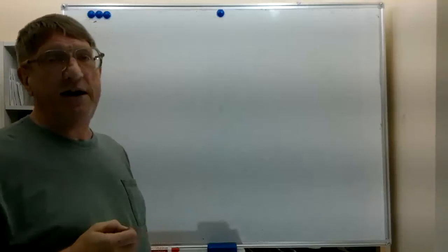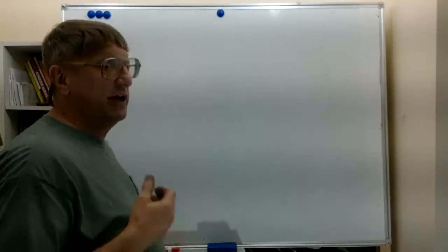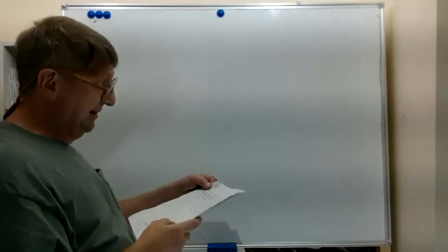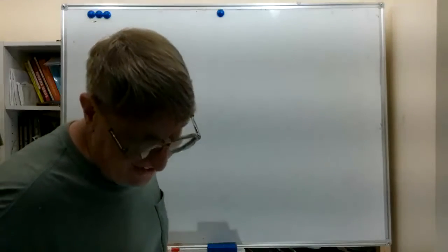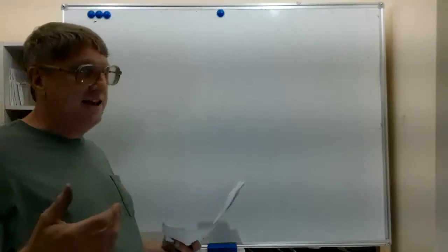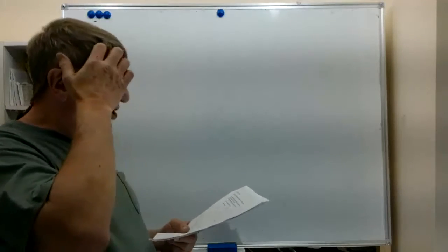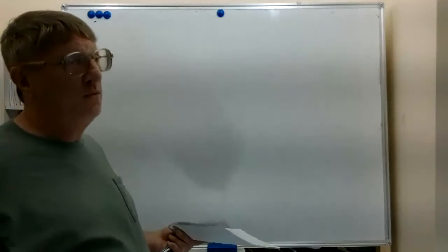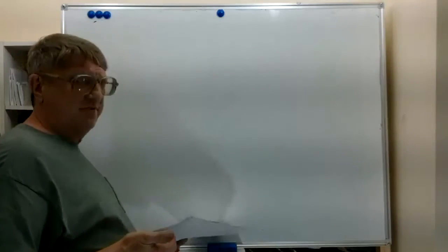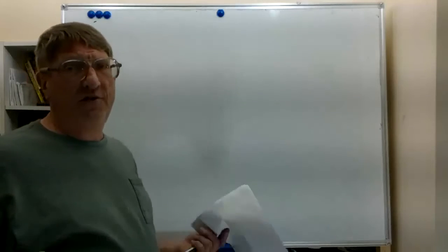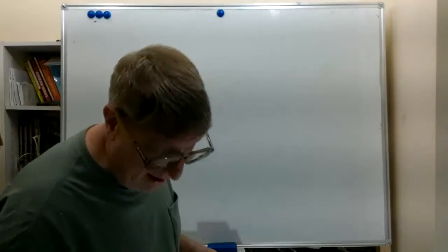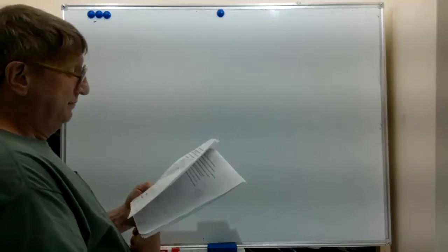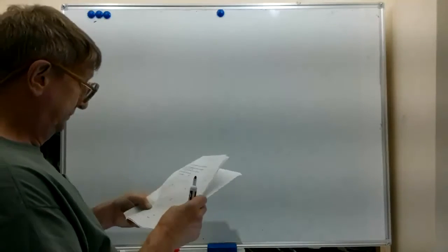This is one of the reasons you might have heard people say, if you're working on a live circuit, keep one hand in your pocket. It's a good rule, but it doesn't save everything. It's not the end-all rule. Really, whenever possible, you want to work on a circuit with it shut off. But certain things, such as voltage readings, are virtually impossible to take with power off.